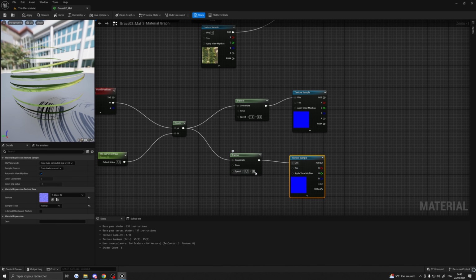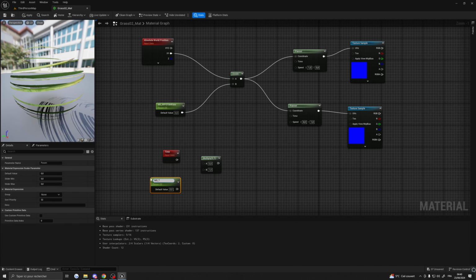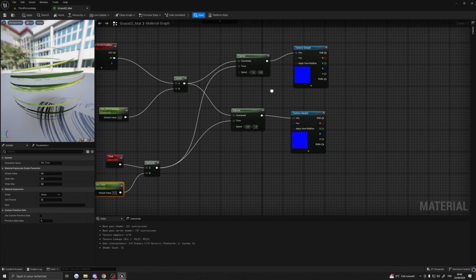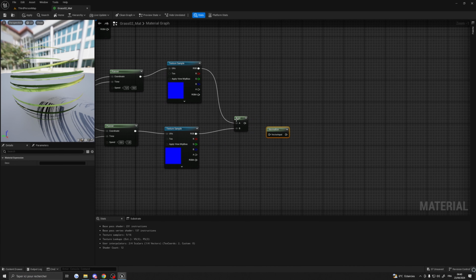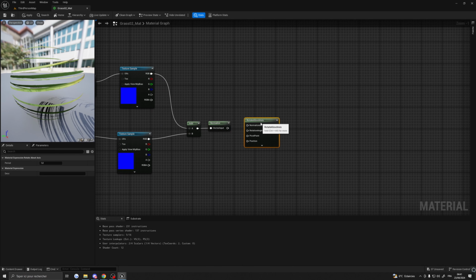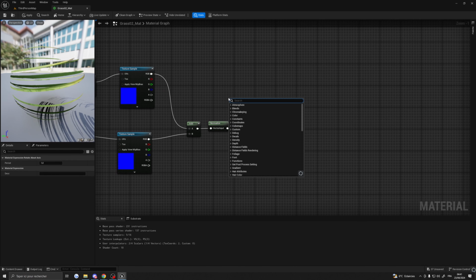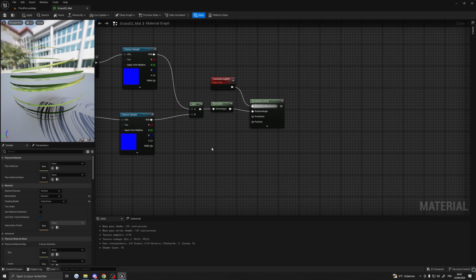Now I'm gonna change the value on the x and the y at the speed of the 2 panners. So I'm gonna take a time node, a multiply, and a parameter called ms underscore time. Plug that into both of the time inputs of the panners. I'm gonna add both of the results, normalize this. I'm gonna bring a rotate about axis node, bring the result in here, take vertex normal, plug that here.